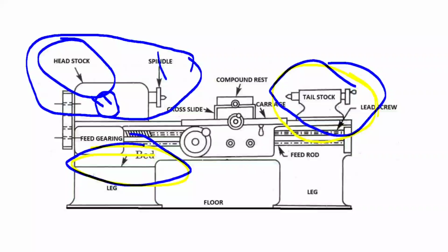First is the spindle, second is the tailstock slide, in which the housing for the spindle is bored, third is the base fitted to the slideways, fourth is the screw and the hand wheel to control the longitudinal movement of the spindle, and the fifth is the tailstock clamping bolts and drive for clamping the spindle. So these are the four to five important parts in the tailstock of the lathe.